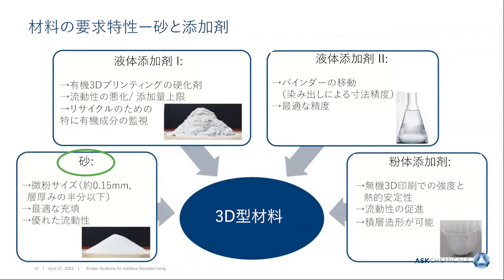It is optimized for packing, since there is no or very little active compaction of the material. It has to pack itself very well to increase density. And we need a good flowability because it is spread out in thin layers. So we have to ensure that this spreading is always functioning well.